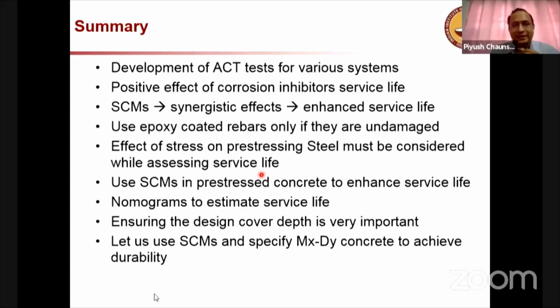One other question. Some tests say that a little corrosion is also helpful with respect to bond with the concrete. Is it true? Good that you raised this point. Yes, it is true up to about 1%.